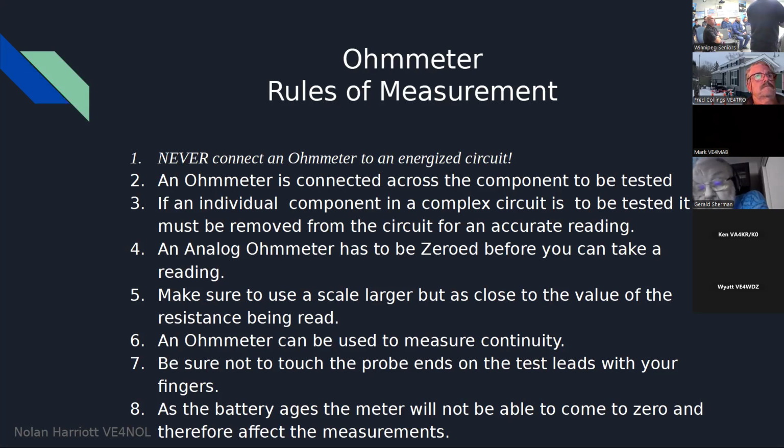Always make sure you're using a scale that's larger but close to the value that's being read. And ohm meters can be used to measure continuity as well, which is basically just a really low resistance reading. Be sure not to touch the test probes while you're testing your components, because your body has some natural resistance, and it will affect your measurements as well.